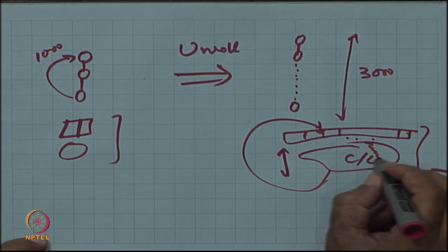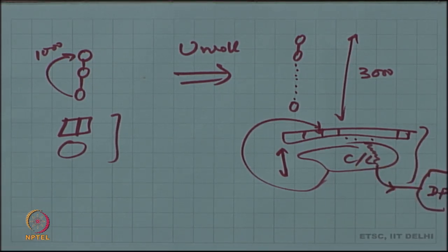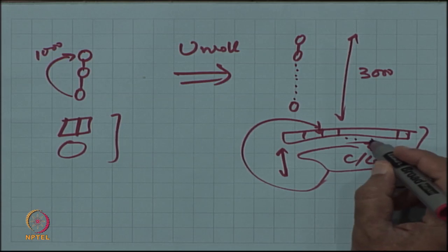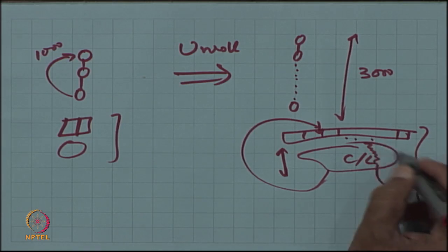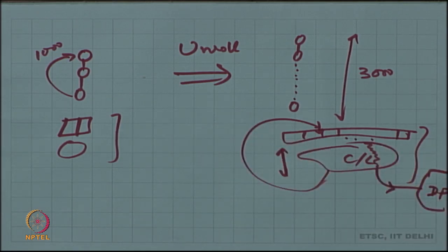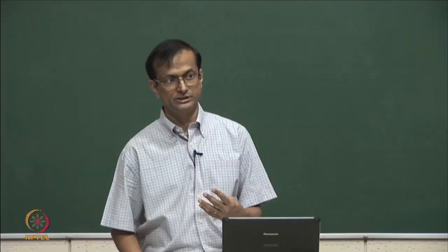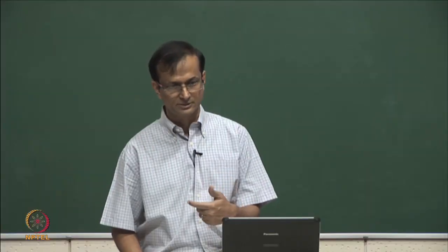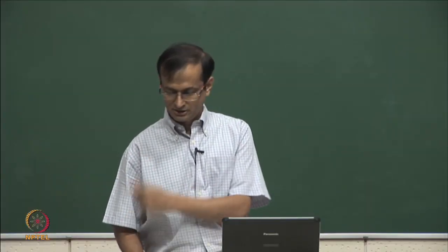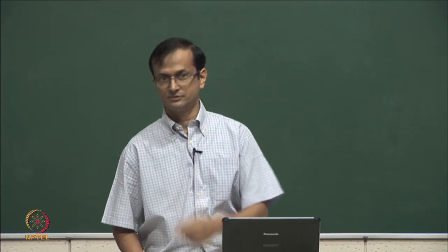So, this is actually part of the clock cycle. You have to allow for the signals to pass through the combinational logic of the FSM and into the data path. Therefore, here that combinational logic was simpler, here it was more complex, and it means that essentially you have to subtract that much from what is available for the data path components. The effective clock width that is available might actually go down in that case where you have a very large FSM.